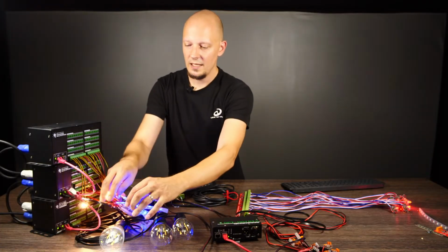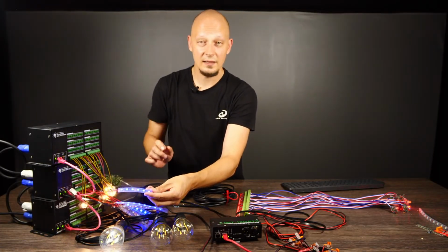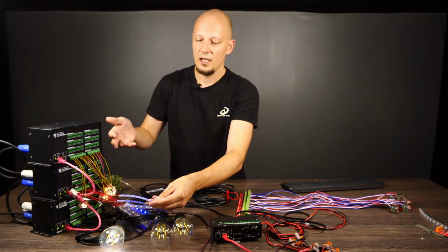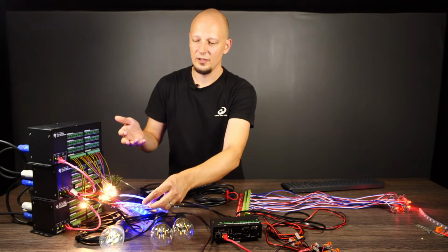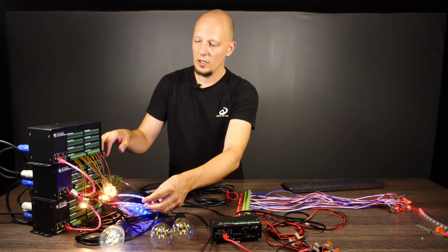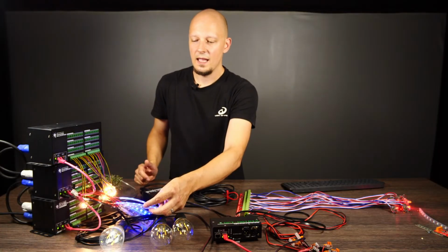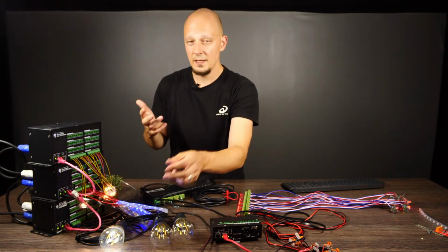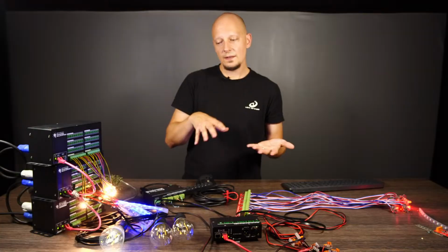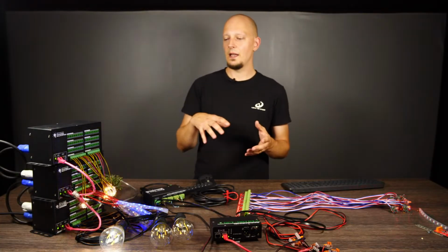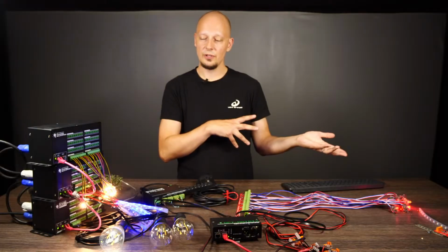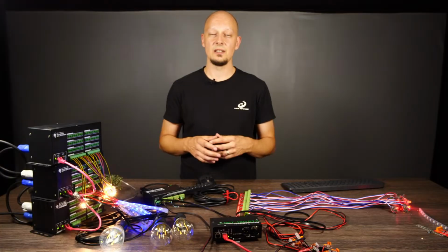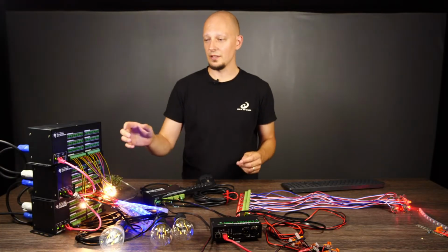As you can see, the length of the segment is not that long. That is because of the limitation of the output. I think it's 65 milliamps for the output, one of the 64 outputs on the device, and hence the segments can't be that big. But on the other hand, you can have the cable or the wire going from the output into your pixel. It can be very, very long. So for 24 volt, it can be even 10 meters or even longer.